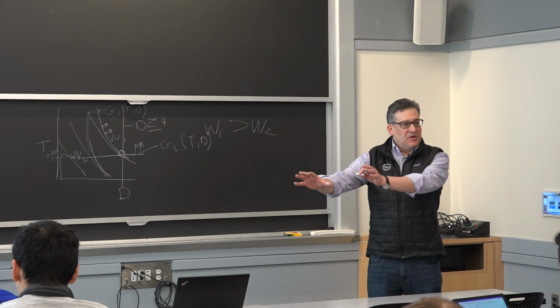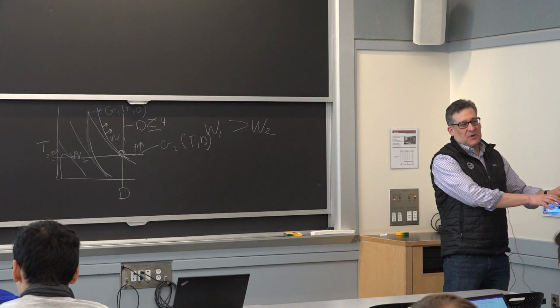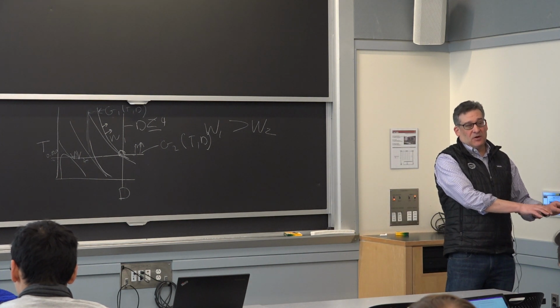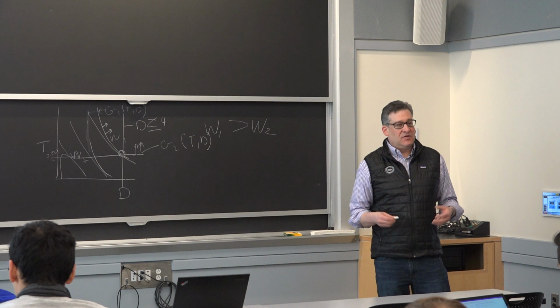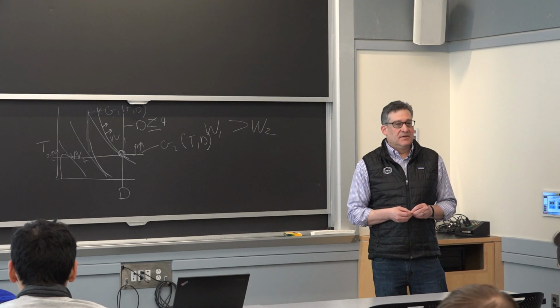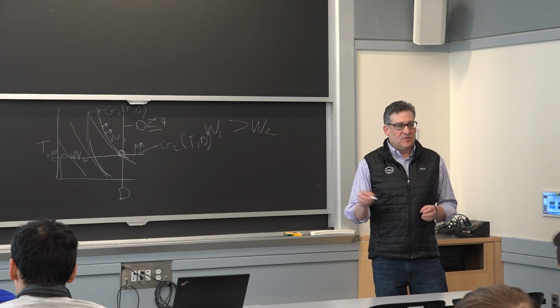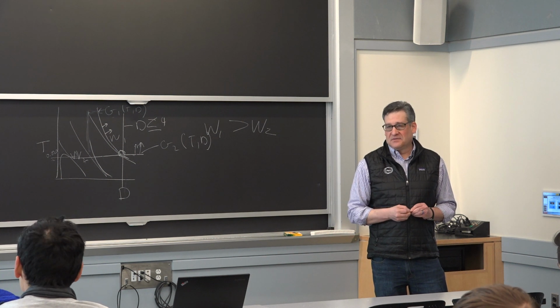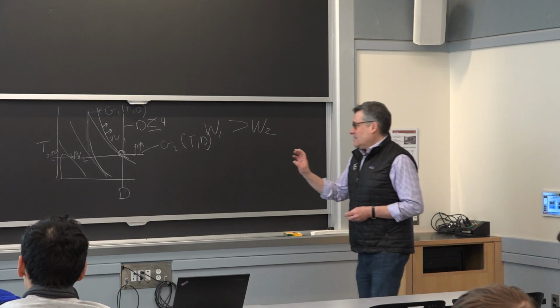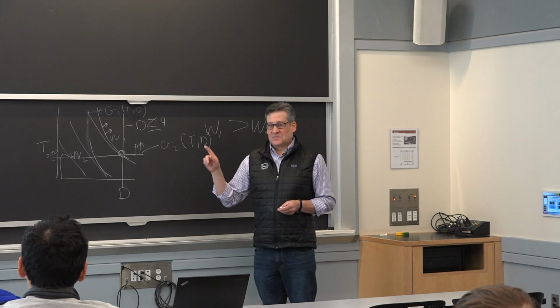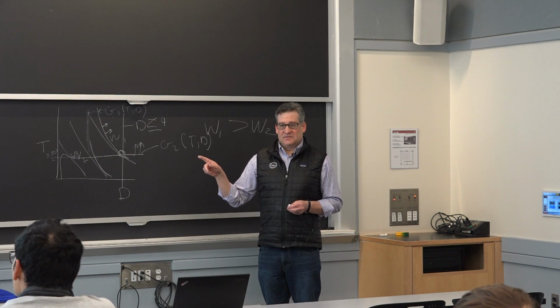They tested over here on the coil, but the part of the coil over here had some defects, and this was actually weaker. So that's why you put in a factor of safety, to make up for those unknowns. And I would hope that in a mechanical design course, some of you, because some of you are MEs, would have discussed this. Okay. Does this make sense, guys? Any more questions on that?